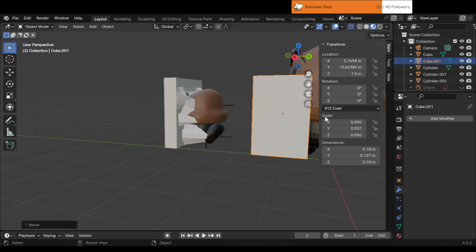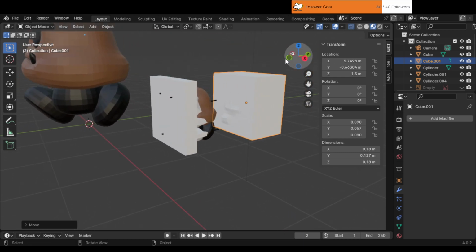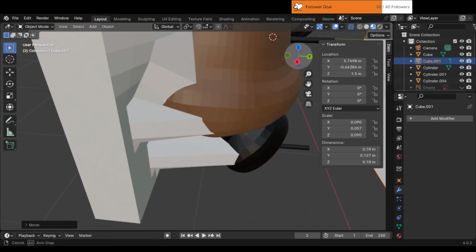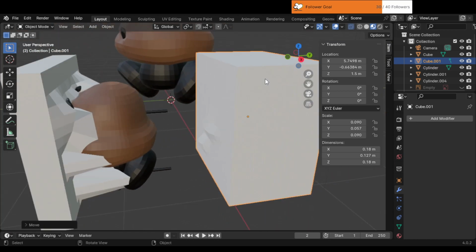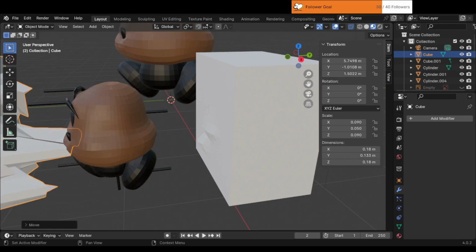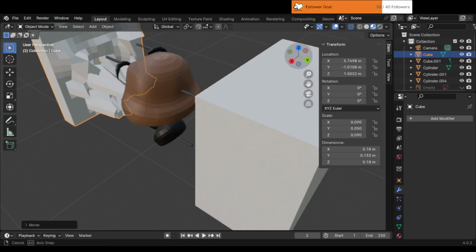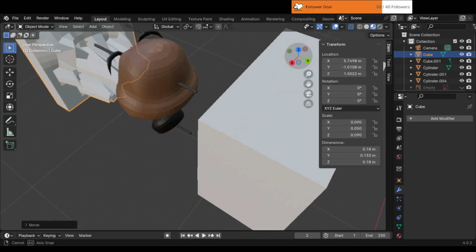4. Prepare for 3D printing. Check mesh integrity. Ensure the wrap mesh is manifold and free of non-manifold geometry, such as intersecting faces or holes. Export. Once you are satisfied with the wrap mesh, export it to an appropriate 3D printing file format, e.g. STL.